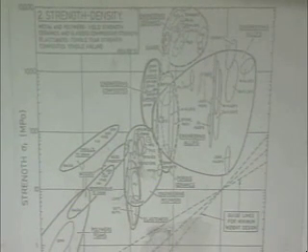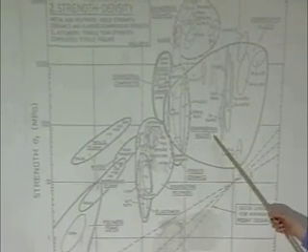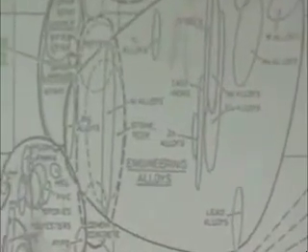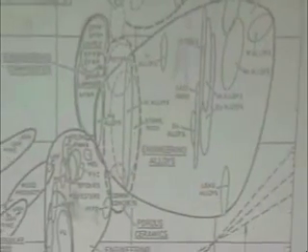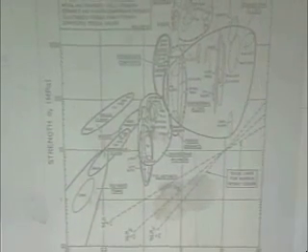We have a lot more ability to change the strength of a material by changing its composition and its microstructure than we did in stiffness. And secondly, that just as before, metals tend to group, composites tend to group, polymers tend to group. So by understanding the prototypical behavior of one material, we get an idea of what's going on in the whole class of material.